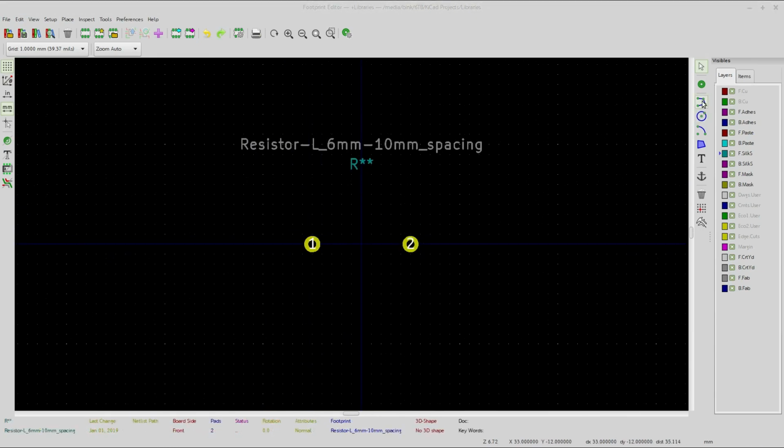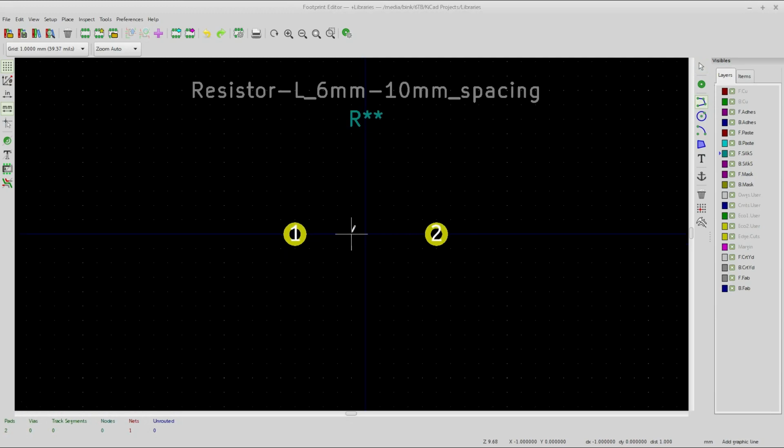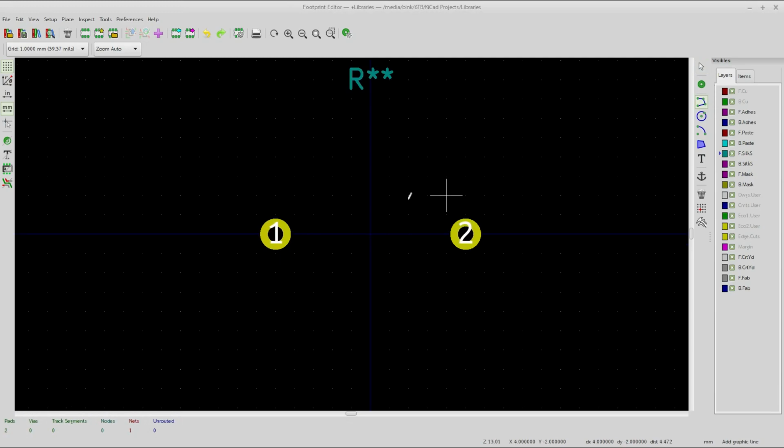And next we're going to draw a box around all of this. I'd say zoom in maybe a bit here and try to keep it as tight as possible to where just the actual component will be enveloped inside of here. So I could draw a box around the whole outside here. That's valid. But remember that this part right here and this part right here are just leads.